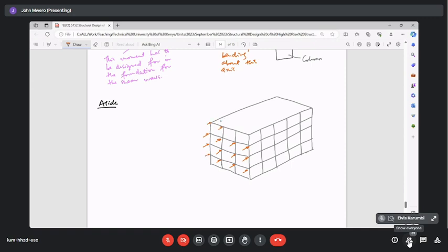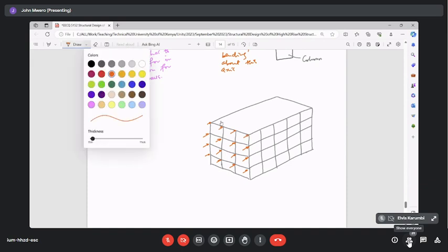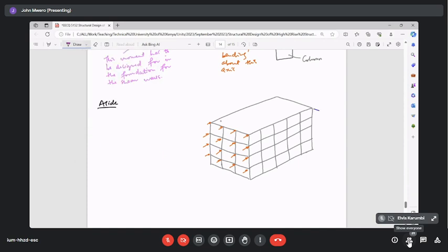These are the forces that we have calculated per frame, which I saw the group that made a presentation yesterday managed to calculate those forces. So X and Y directions. You come and just put them as point loads at the nodes because they are loads per frame. So at each level, whatever load per frame that you have calculated, you come and put it in there, in the X and in the Y direction. So you do this for wind and you do this for earthquakes.